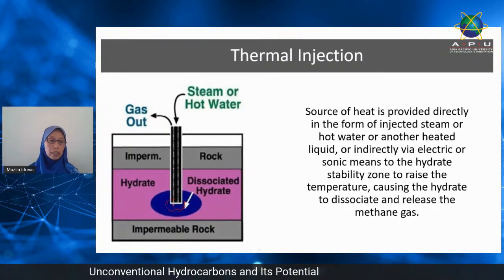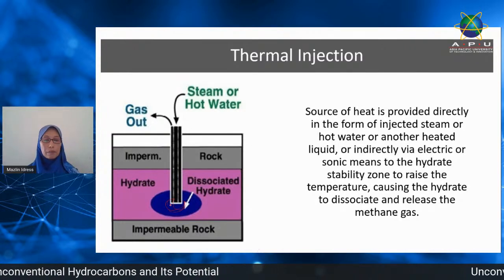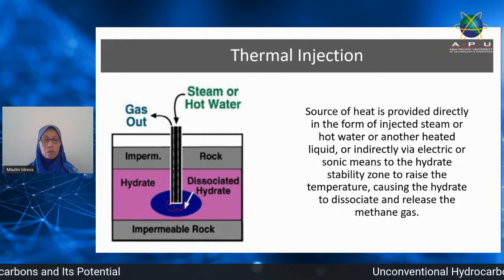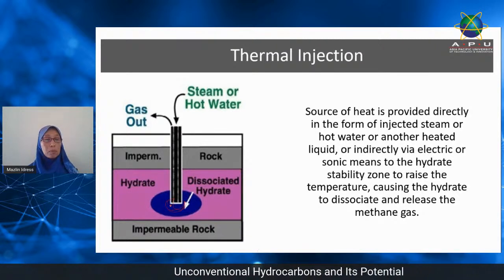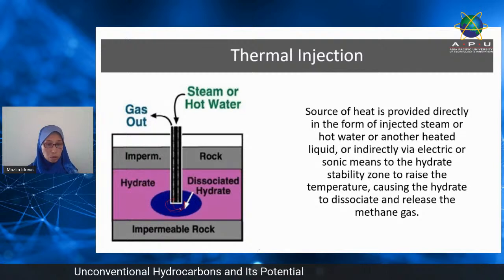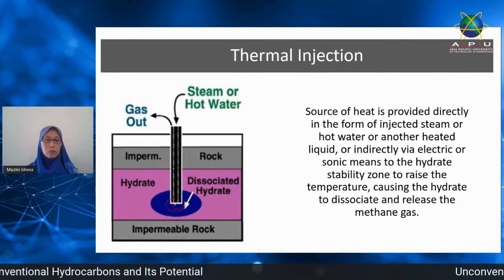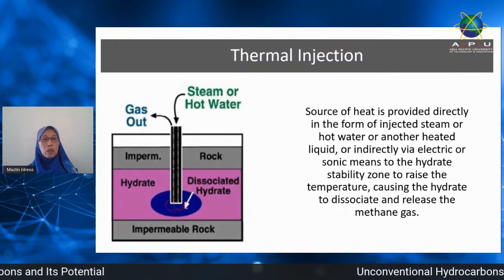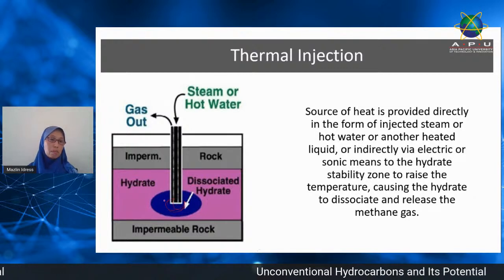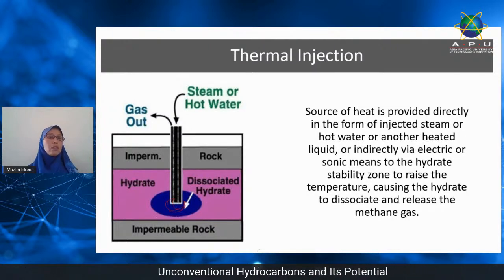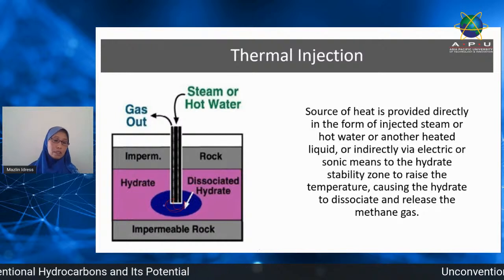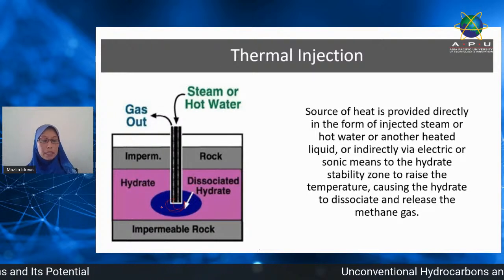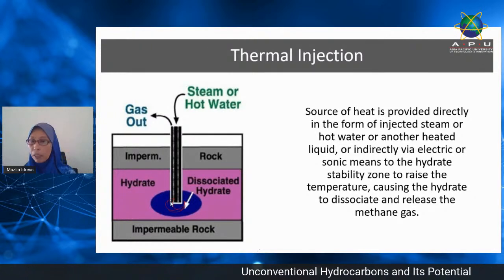And for wellbore heating, we are installing a heater or multiple heaters inside the downhole to increase the near wellbore temperature. Due to the increase in temperature, the gas hydrate is going to dissociate.